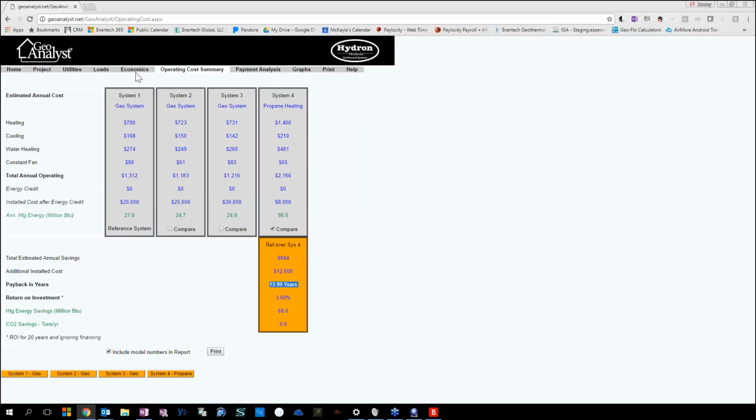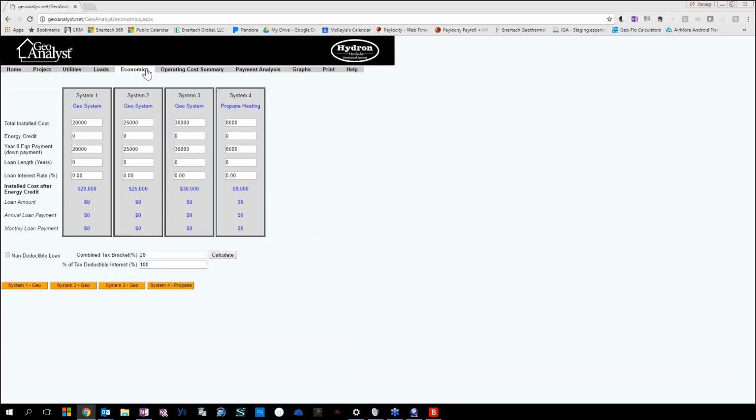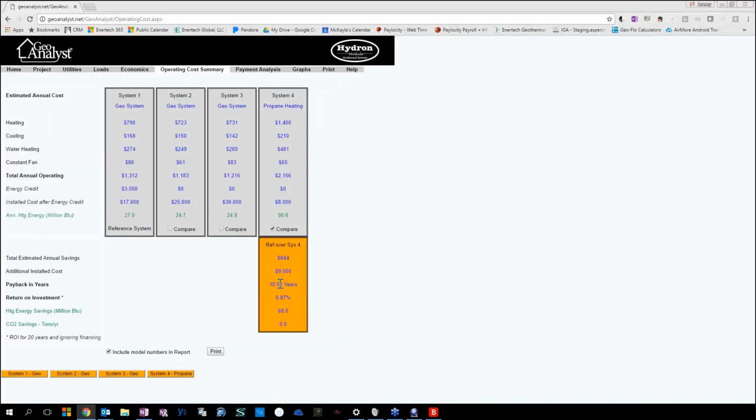It might last a little bit longer, but it's just not a good decision. Now, if we bounce back to the economics page and consider some incentives, let's take a look. A $20,000 install project with a 10% tax credit, they're going to get a $2,000 tax credit. And let's say they get $1,000 from the utility company. That's a pretty low number. So here in this example, we have a $3,000 total incentive. And let's take a look. 10.5 years on that example. And that's $1.30 propane.